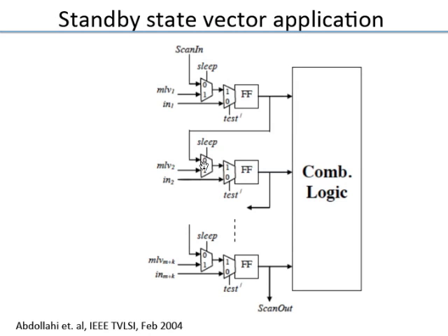And now it turns out that one mux is always there. That is for what is called scan testing. Scan testing is where you serially chain these flops. So when you want to test this combinational logic block, when you manufacture the chip and the chip comes back, you want to check if everything is okay or not.